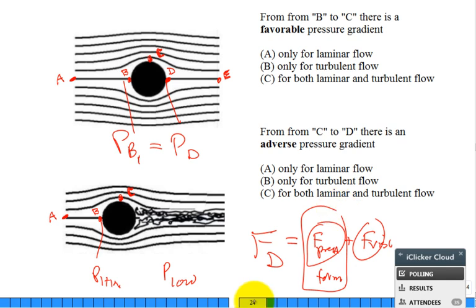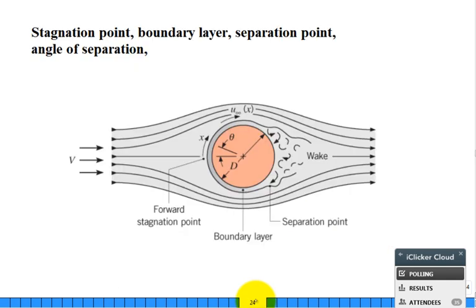Okay. Well, this whole separation point concept, it's quantified by this angle of separation theta. In this textbook, they use theta. And so it could be where it's up in this region where it separates, or where here it looks like it's separating a little bit above, past 90 degrees. But if you go to really high flow rate, the size of the wake reduces.